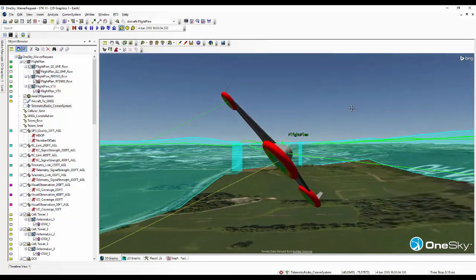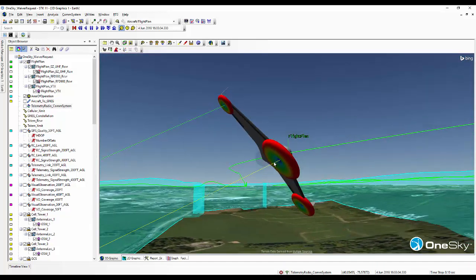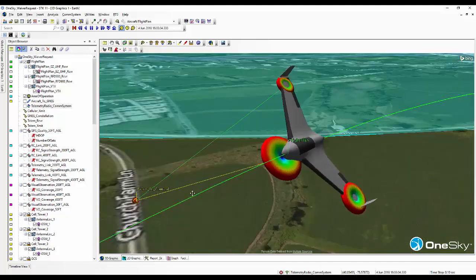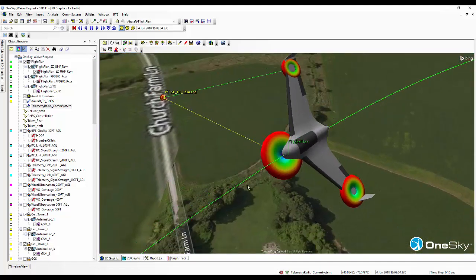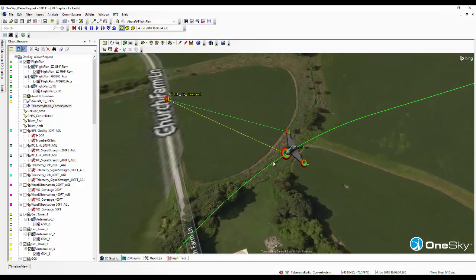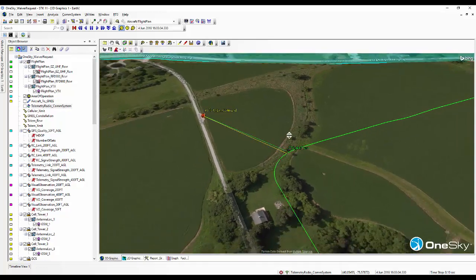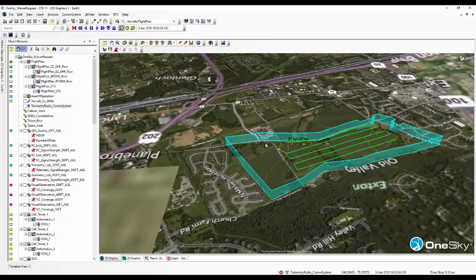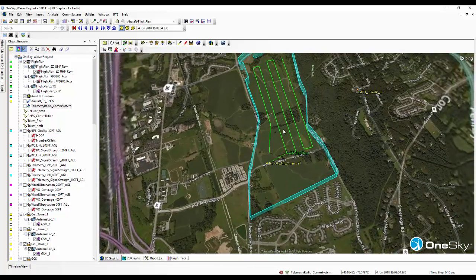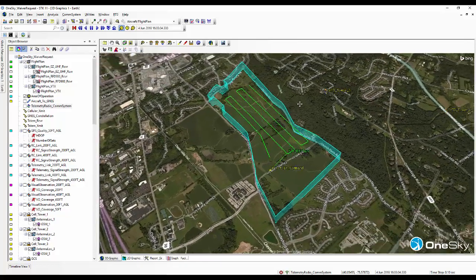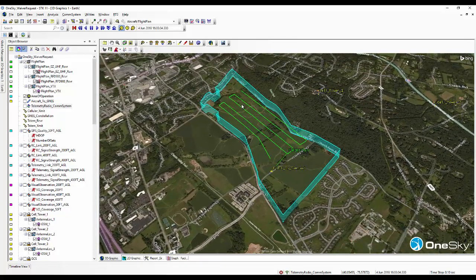My FPV antenna, you can see that link directly right here, is really going through a null in my antenna gain pattern. Right? So I can really understand some of the things that I may want to do to mitigate those situations, like limiting my bank angles and things like that. So it's interesting to see those specific situations and understand those limitations of the systems.